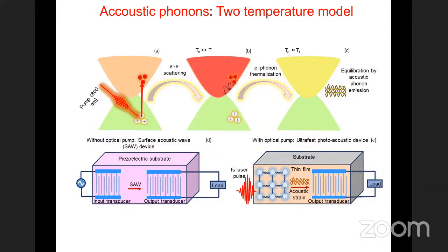So what are the implications of this demonstration? We have the surface acoustic wave device, in which we have an input transducer and output transducer, in which the strain is induced by some mechanical means and converted at the output transducer into some electrical signal. In this case too, the femtosecond laser pulse induces some mechanical strain, which appears in the form of acoustic strain and can again be detected by the output transducer. Using femtosecond laser pulses of different frequency and intensity would induce a different strain. So this SAW device can be replaced. Of course, we need some more demonstration with different wavelengths of radiation and different intensities, but there's a definite possibility that this device can be replaced by ultrafast rare earth nickelates illuminated by ultrafast femtosecond laser pulses.